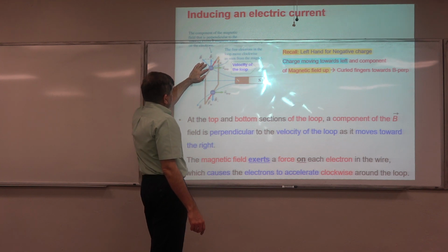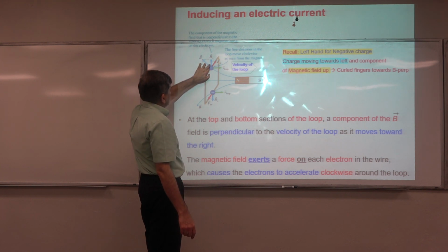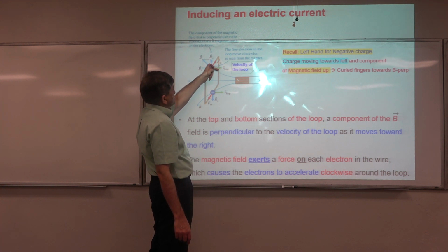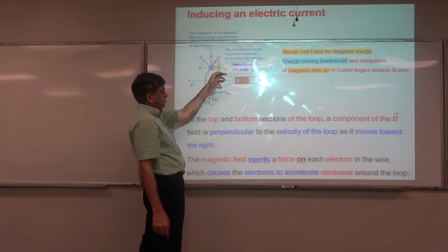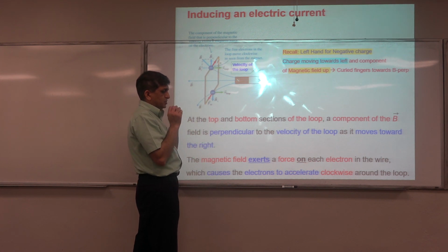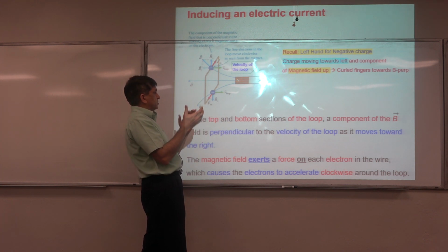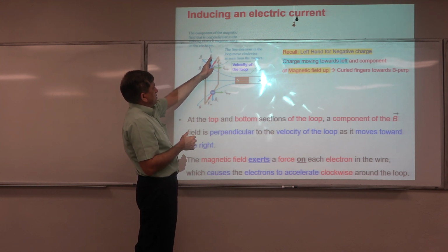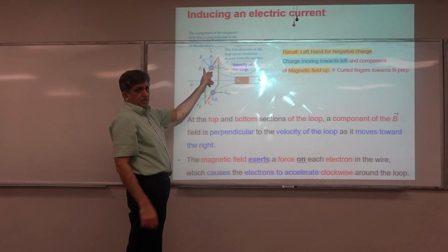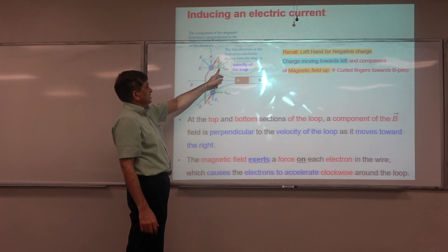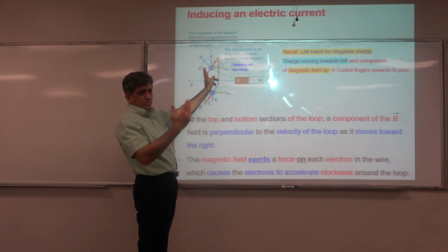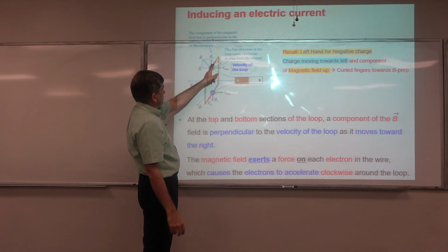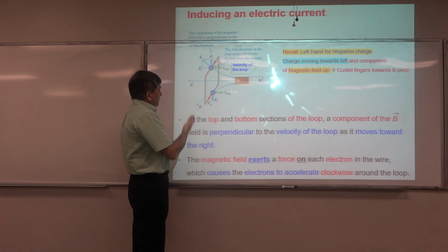Now with this magnetic field, the vertical component of the magnetic field is here, and the velocity component is here, the motion of the charge, because the conductor has charges in it. So when I move the conductor, I'm moving the charges in it, right? So I take the perpendicular component, because if I take the parallel component, the velocity vector and the magnetic field are along the same line, so there is not going to be a force. Only the vertical component of the magnetic field matters.